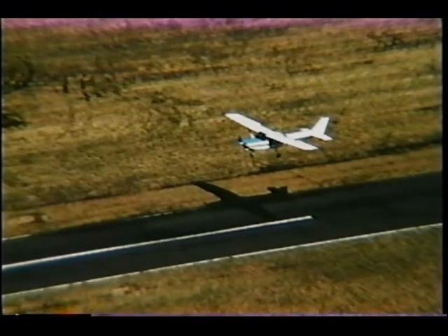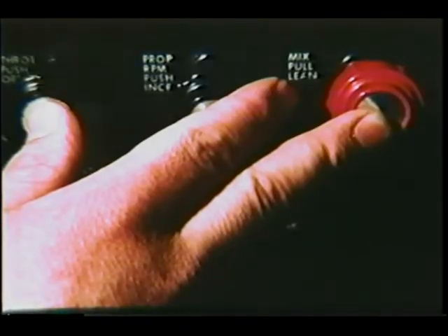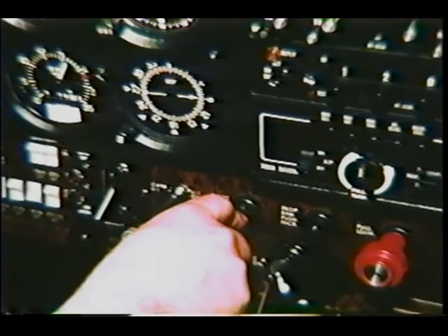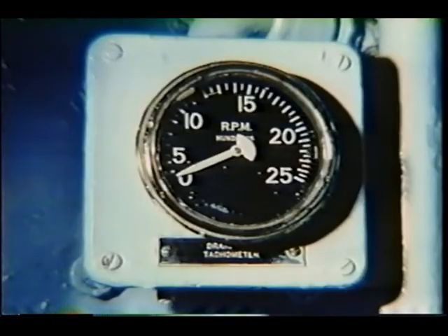Now, when you actually take it around, first and foremost, fly the airplane. Forget the tower, forget the Unicom, forget the passengers. Sure, they've had a lot of coffee and need to get on the ground. They always do, but just fly the airplane. Make sure that you've applied full takeoff power and that it stays there. Engine vibration can cause those power controls to inch backwards, or a defective gauge or sensor can make you believe you've got full power when you don't.